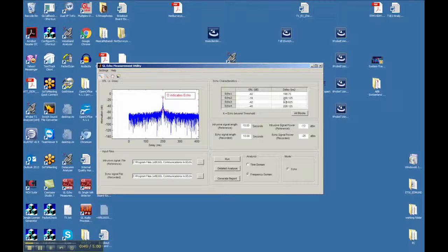We had taken a file, created another file with an echo at 200 milliseconds of delay, front-end delay, which means that everything gets slid by 200 milliseconds. So there must have been a strong echo at 200 milliseconds. We further attenuated by 10 dB, and exactly that's what the ERL says. It's about 10 dB down. So this is how the EMU works.